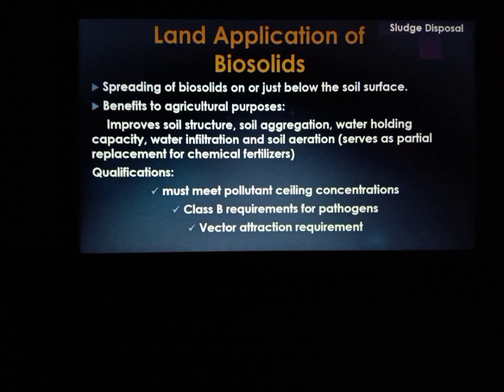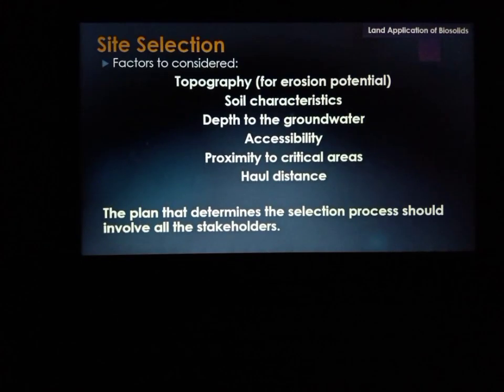The application to land for agricultural purpose ay nakakatulong dahil yung organic matter na present sa biosolid or wastewater improves the soil structure, soil aggregation, water holding capacity, water infiltration, and soil aeration that serves as a partial replacement for the chemical fertilizers. For this disposal, qualifications must meet the pollutant ceiling concentrations, Class B requirements for pathogens, vector attraction requirement.